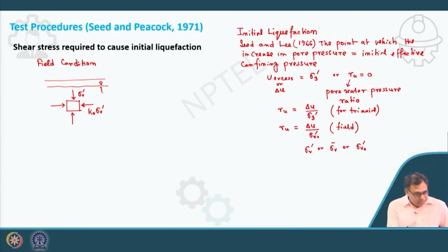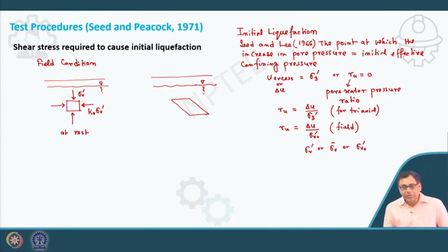So, now for the field condition you can see, this is my initial condition, the at rest condition, that means the seismic load is not applied. At rest condition, this is your soil element and these are the stresses acting. Now, when the same soil element has shear stress acting because of the ground shaking, so this is at rest and this is during ground shaking.